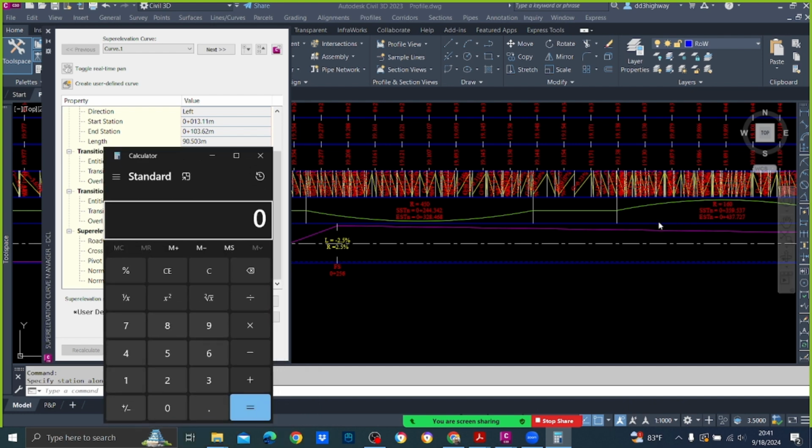Here the starting station is 359.537 minus, and the end station is 328 plus 468. Then it is 31. Okay, so here, for this one to go down and come back, you want a minimum of how much? You want 48 minimum. Why? 24 outside, 24 outside. So in that case, you have to consider this as a